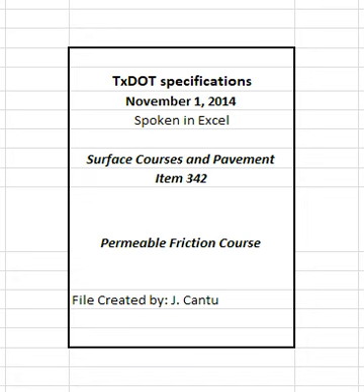4.7.3.1.2 Thermal imaging system. Review the output results when a thermal imaging system is used, and provide the automated report described in Text 244F to the engineer daily unless otherwise directed. Modify the paving process as necessary to eliminate any recurring, moderate or severe, thermal segregation identified by the thermal imaging system.